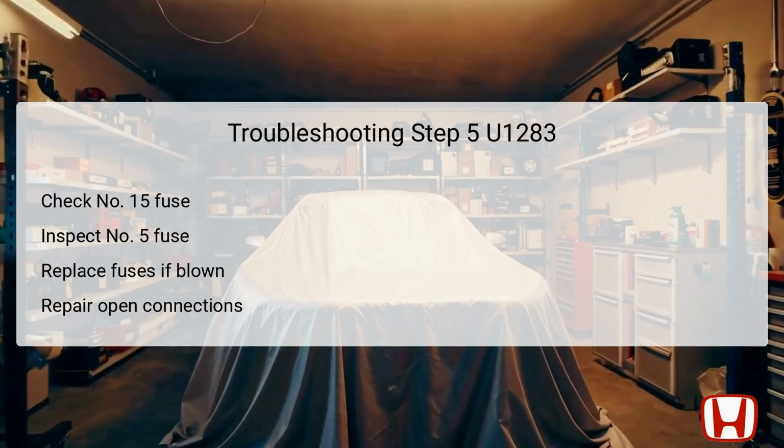Inspecting these fuses is vital since a blown fuse can lead to loss of communication between essential components. If the fuses are working, you might need to repair any open circuit or high resistance within the circuit for either fuse. If one or both fuses are blown, simply replace them to restore functionality. However, if the new fuses blow again, it indicates a short circuit issue in the wiring, which will require further